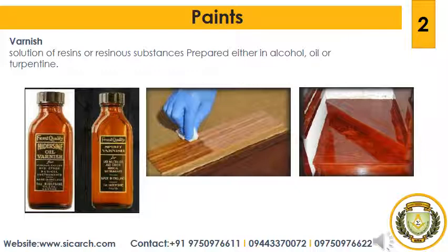The fourth type of varnish is water varnish. The shellac is dissolved in hot water and enough quantity of either ammonia, borax, potash or soda is added and the shellac is dissolved. These varnishes are used for varnishing maps and pictures. They are also used for delicate internal work and as a covering for wallpaper.